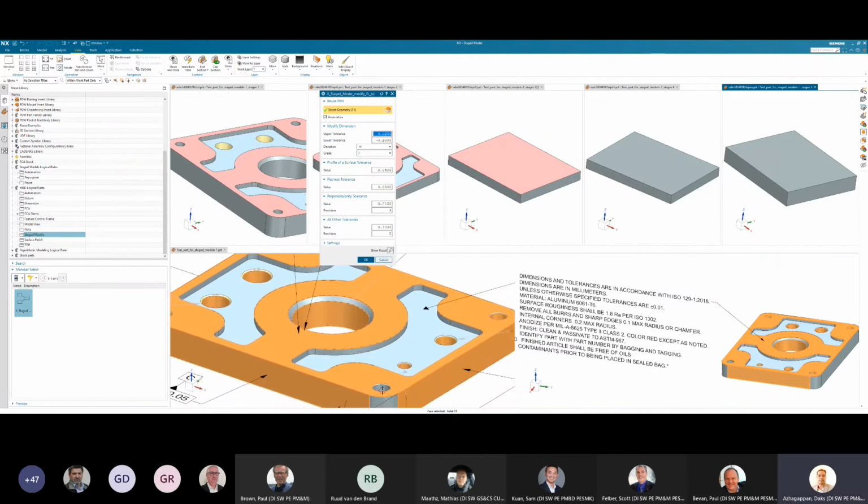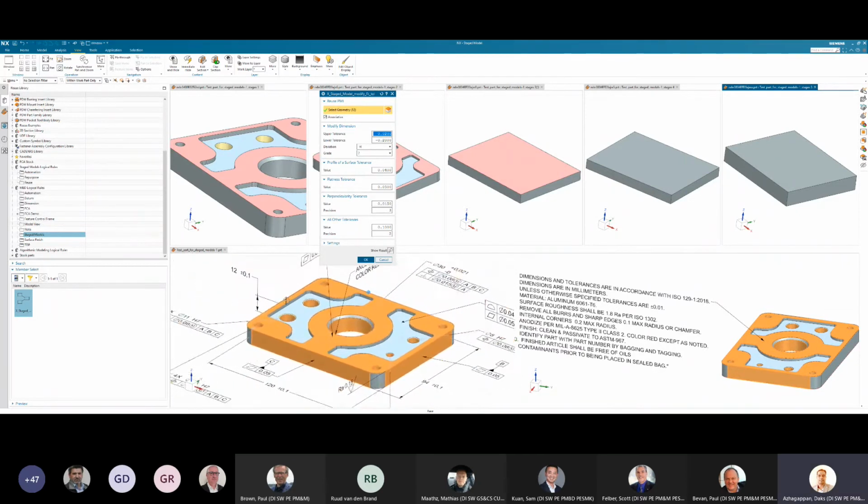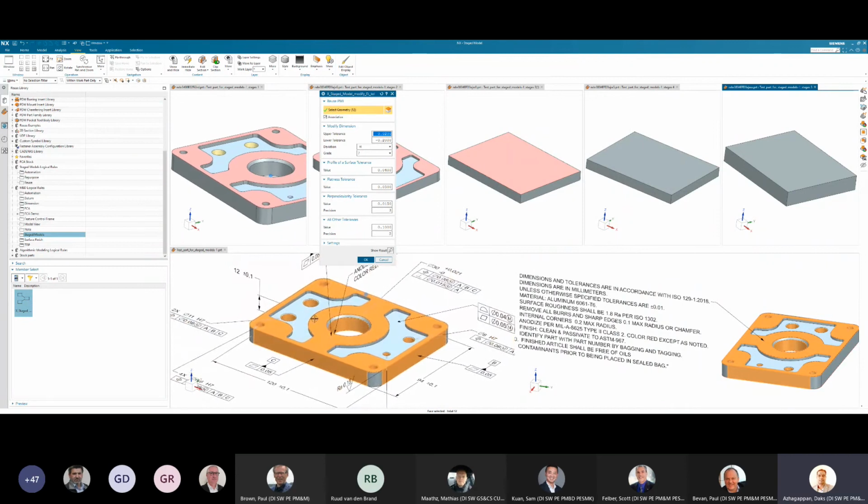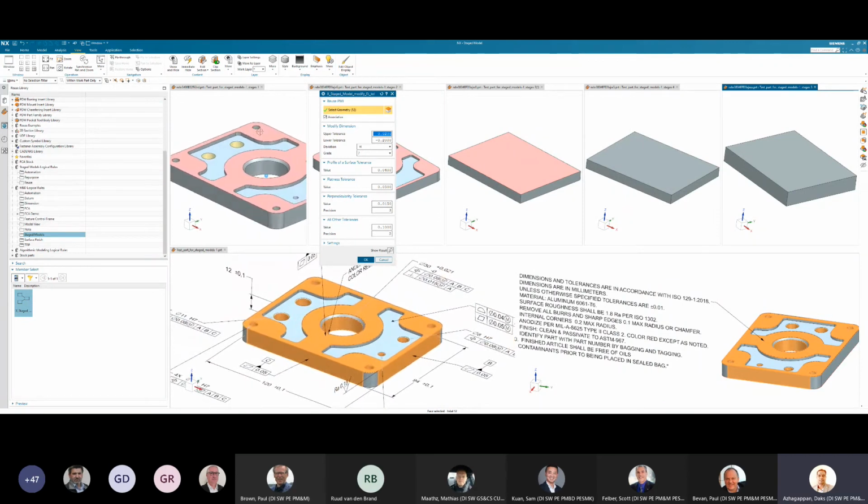So you can see that I'm not reusing. I'm just saying, okay, here are those faces I'm machining, all those holes. At the same time, that's what I care about. Everything else is built in here. If you want, you can even adjust the grade tolerance information. Say 0.15 if you want, or probably 2.5, right? Oops, sorry. It's 0.2.